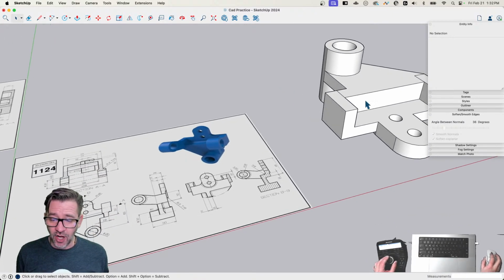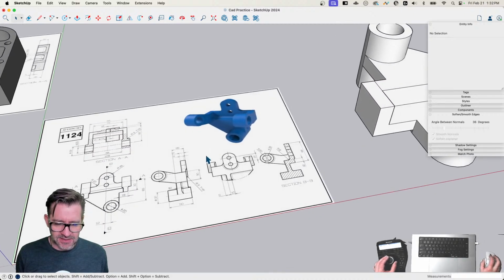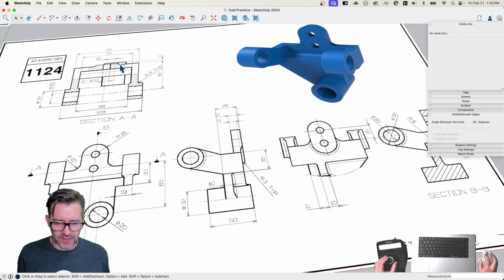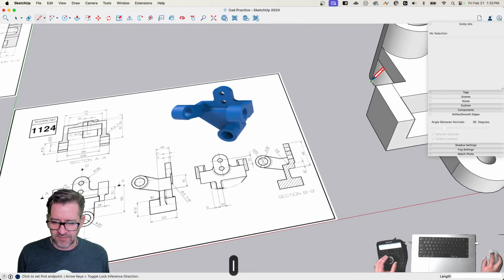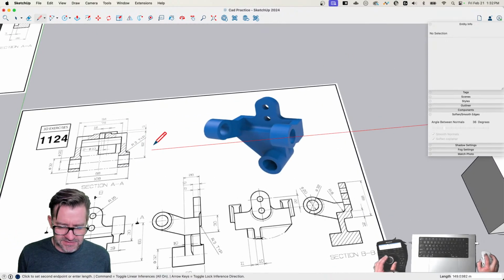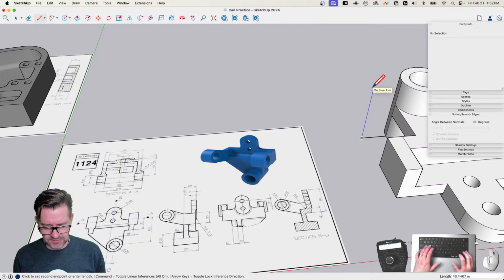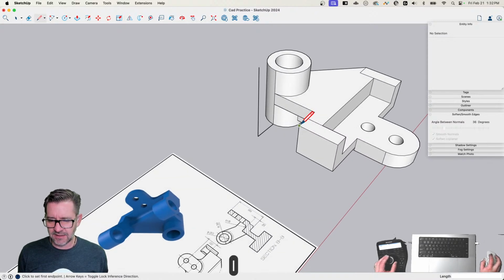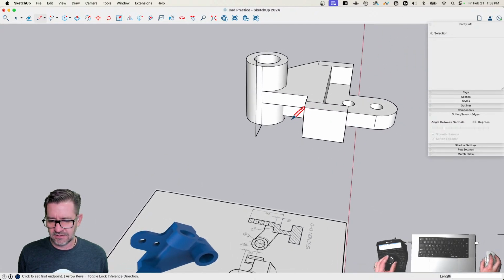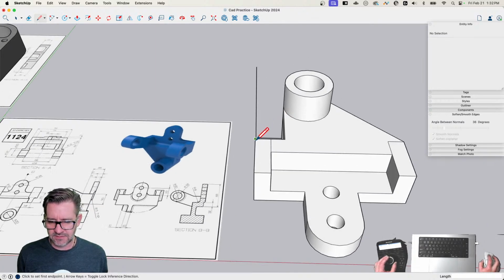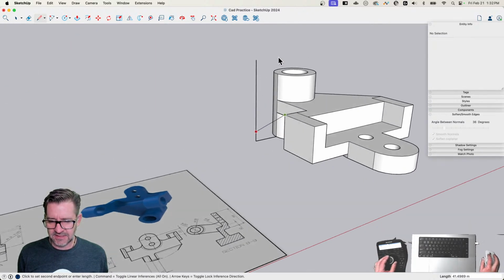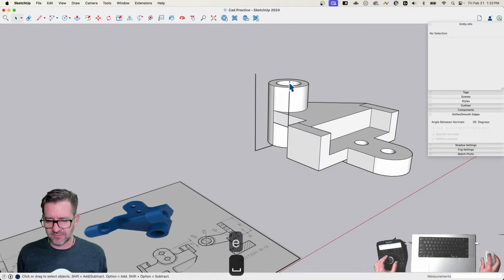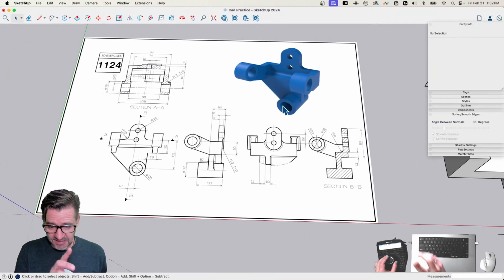All right, so I did all of that because I'm trying to find the middle of this circle, and the center of that is pulled off of the bottom of this piece. So if I come right here, if I come up 62, that's how high it is, and it is aligned with this right here. So that means if I take this now straight up to that point, that's where the center of my circle is. And everything else is located based on the center of that circle.